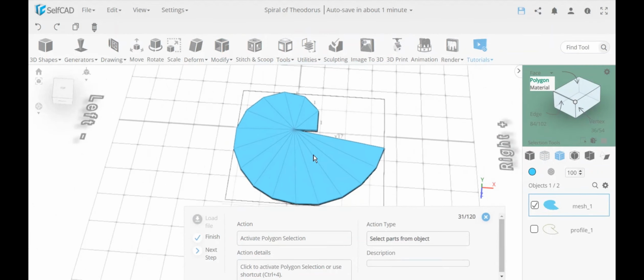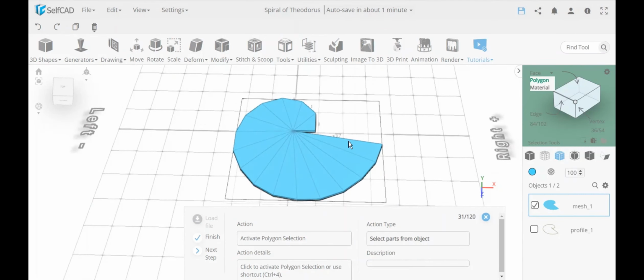What happened is that in polygon modeling applications, many of the tools such as extrusion, fill polygon, and some other tools work with something called Delaunay triangulation or constraint triangulation, which basically means that every vertex you give it is used to create triangles. It's a term used because normally there are triangles, but it could also be quads. So it's either triangles or quads, but it's still called triangulation even if it's quads. That's the way the name stems from triangles.